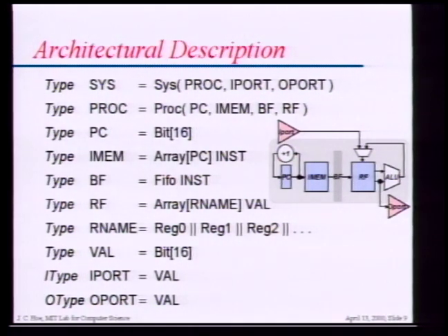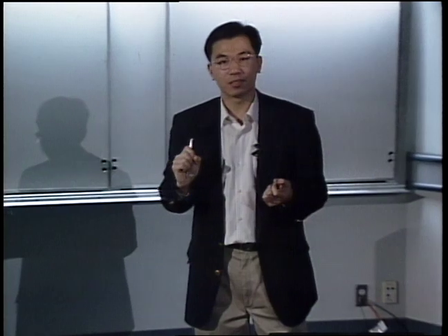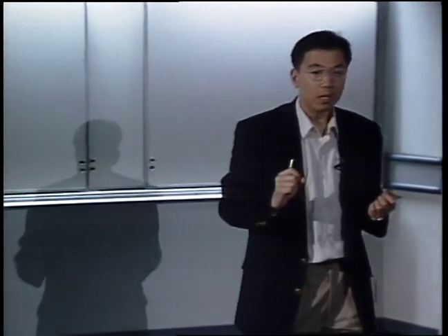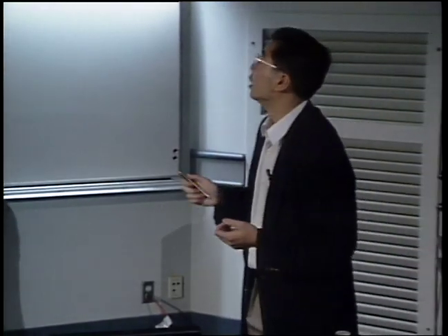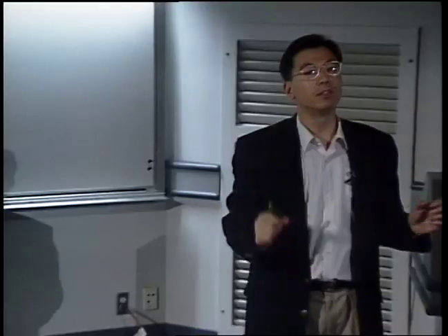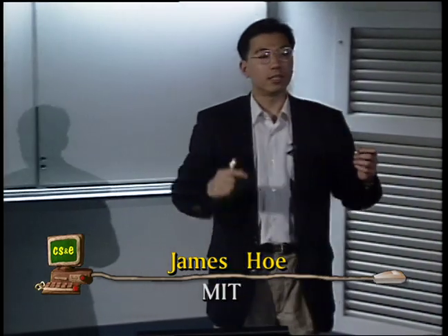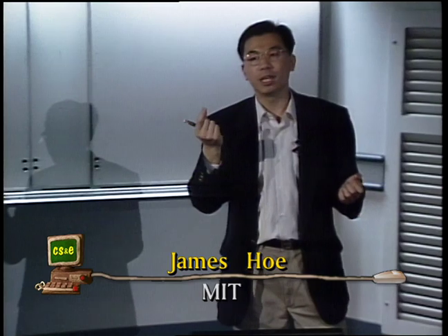So in our design abstraction, we're going to use FIFOs that are bounded but with unspecified size. What this allows us to do is describe the behavior of this pipeline processor, in the two separate stages independently with the FIFO in the middle of isolation. And only at the very end of synthesis do we instantiate a special FIFO implementation that only has one register in it to get a fully synchronous pipeline implementation out of this.